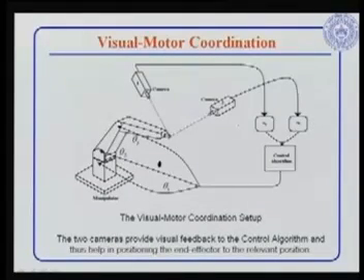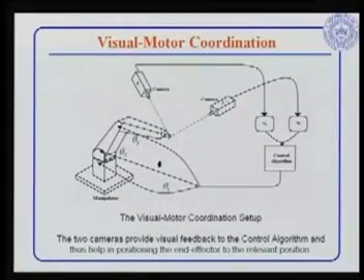So what I said is that the camera finds the end effector position. Even if you take a photograph of a 3D point, the camera has only a 2D point. So it has u1, u2 for camera 1, and u3, u4 for camera 2. So you have this 4-dimensional input vector for a given end effector point, and given the target, the objective is that the control algorithm should find out what theta 1, the base angle, should be, and theta 2 and theta 3, the joint angles, such that by orienting theta 1, theta 2, theta 3 properly, this end effector will exactly reach this target point.